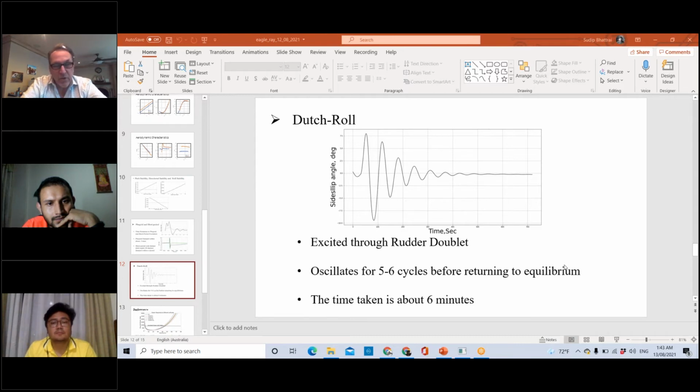Yeah. So one thing you could also do, in X-Plane, it will let you put a little auto flight control thing. You probably know this. You can put a little yaw damper in, and you just tell it how many degrees of rudder per degree per second of yaw rate. And you might just play with that a little and see if it makes the airplane fly right. That'd be a good indication that the autopilot should be able to handle it nicely.